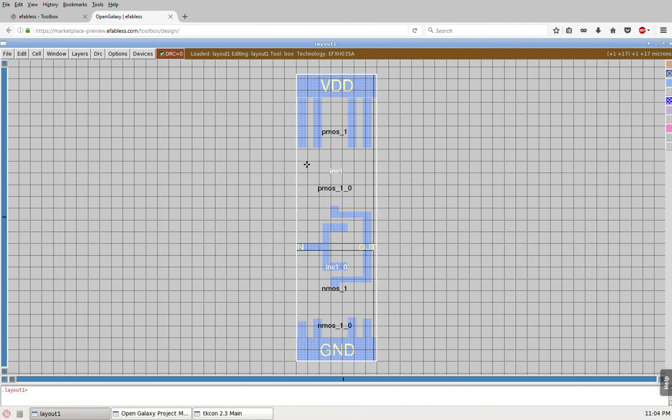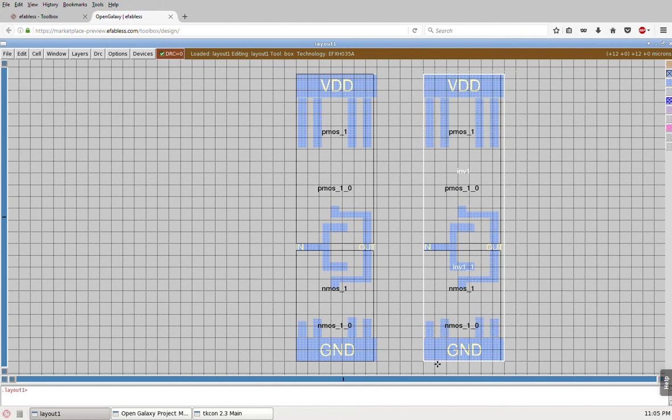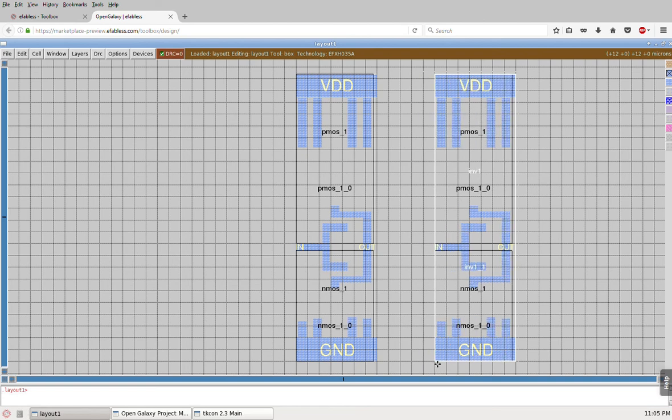What I'm going to do right now is make a second copy of that cell, though it's not going to be exactly overlapping. I'm going to put it a little bit out, just space it out to show some wiring capability of Magic. So the cell right now is selected. It's INV1, lower left corner is over here, which is the point of origin of my cell, and I want to copy it exactly at this location. So when I hit C, the lower left corner of that cell is going to go precisely here, and there it is. I can use the left arrows to move it by 1 micron, which is my grid. It's moving by grid units, left and right using the left and right arrows, up and down with the up and down arrows, so I can easily adjust.